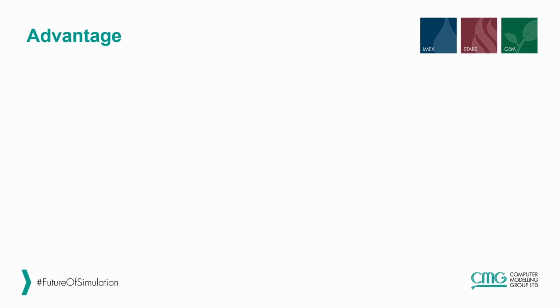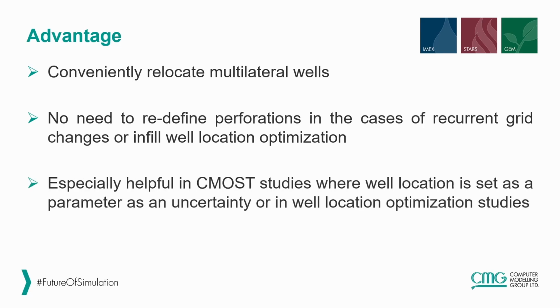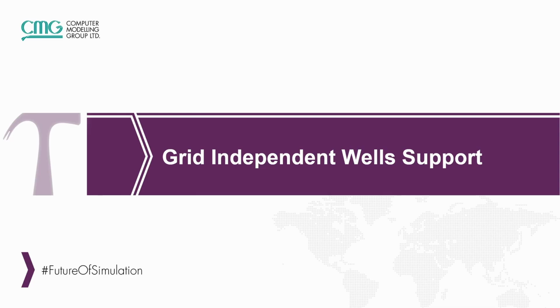Some of the advantages that can be pointed out for the grid-independent well option are that it's easier to reallocate multilateral wells. It's not necessary to redefine perforations in the case of recurrent grid changes or infill well location optimization. And this new option is especially helpful in CMOST studies where well location is set as a parameter in optimization or uncertainty study. Converting grid-based wells in existing models to grid-independent wells can easily be done using Builder 2022. Let's show you a demo about how to create grid-independent wells.